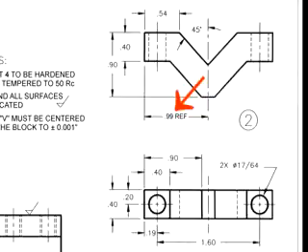This is an older way of indicating a reference dimension, but it's still widely used. The 990 thousandths dimension is indicated as a reference dimension because it can be found in two ways. There's obviously the one that we're looking at, 990 thousandths of an inch, but I can also find